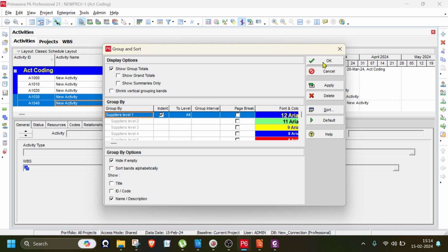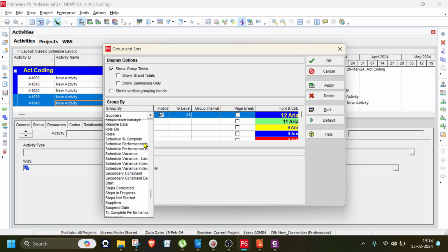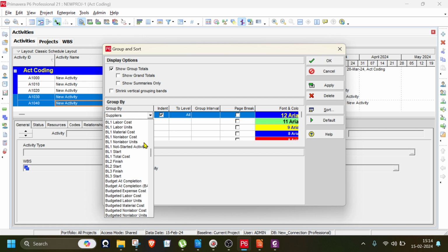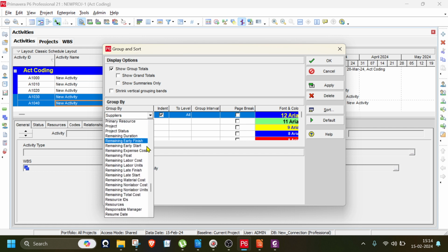Sir, create one coding, any one coding. Just create six activities and all are FS relationship. If it is FS relationship, what do you have to do? Highlight everything, right click, link activities, update the project. So predecessors will come automatically.